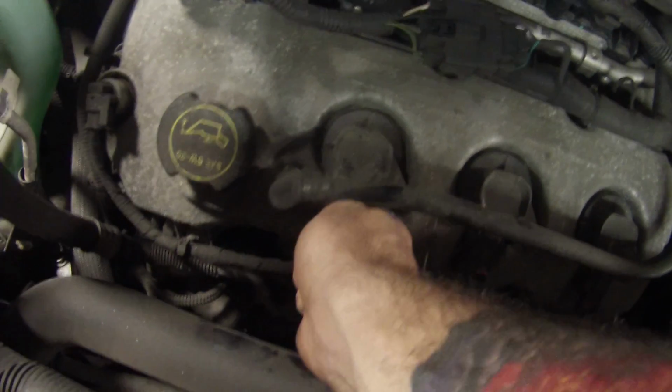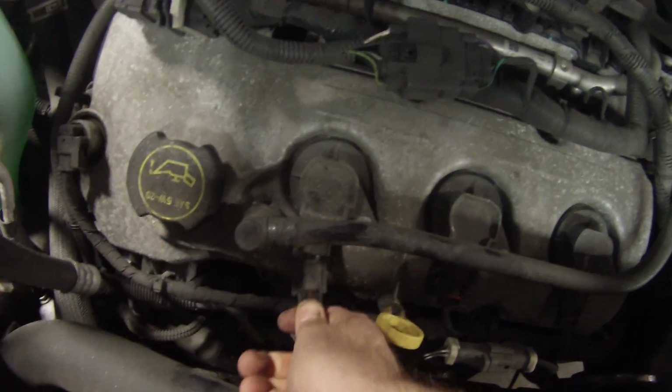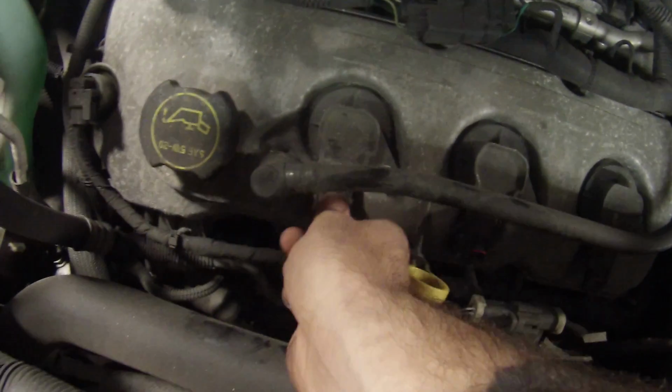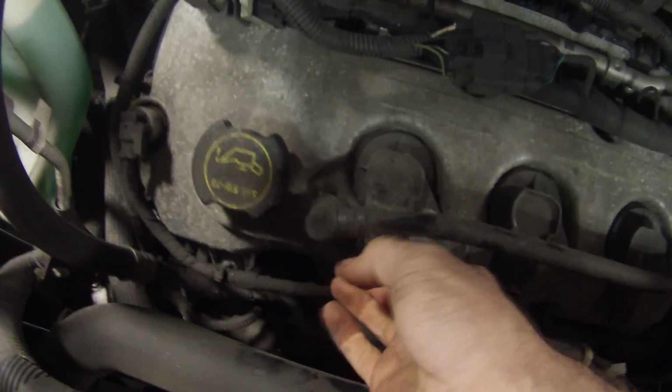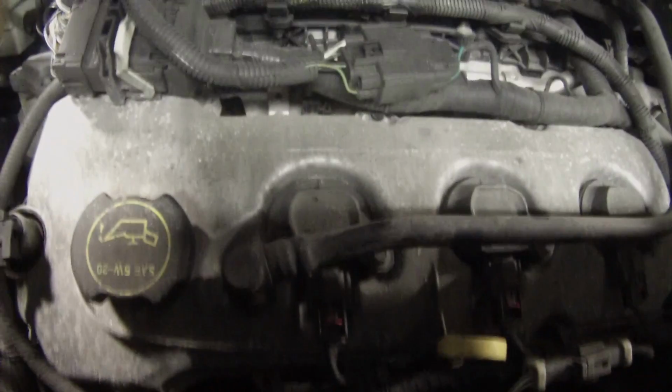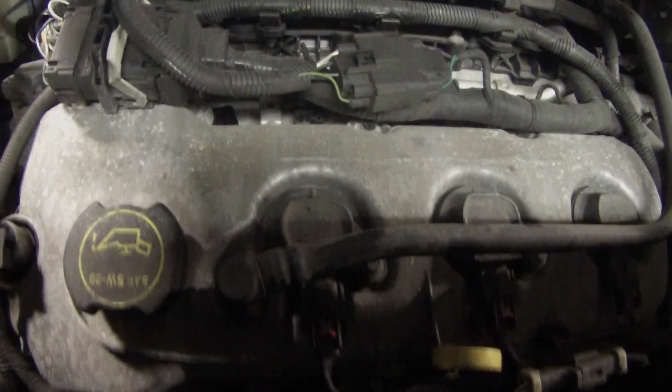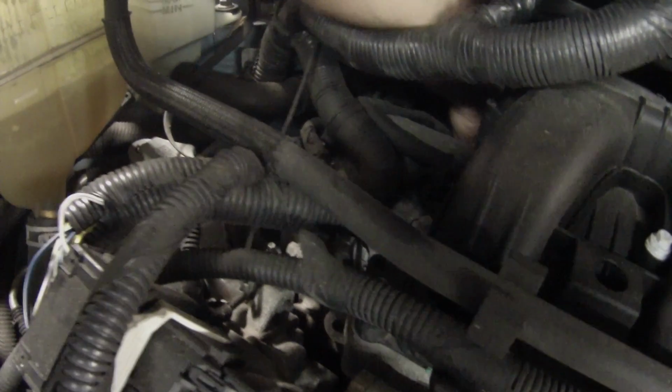Get this clip off. Yes, another RPM drop. Plug that back in, and the only other one that I can get to is maybe back here. I don't know if you could see that shake. It's definitely misfiring. And that one's unplugged and there's no change.